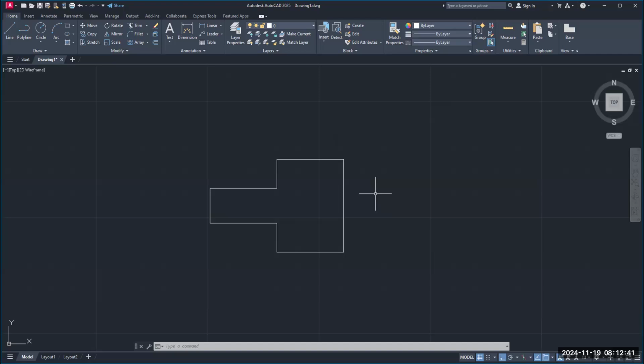but there is a command in AutoCAD, it's called snap angle. Type in SNAPANG. So snap angle, enter, and it says enter a new value for your snap angle. Type in 75 and then enter. And you'll notice that your cursor has now rotated at a 75-degree angle.